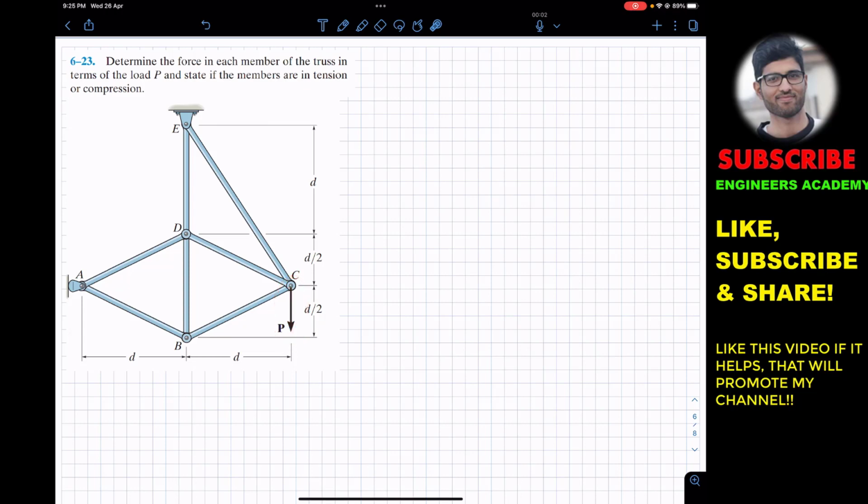So first of all, we will consider the whole truss and we will find the support reaction. So at E, let's say that we have EX reaction, which is going towards the right, and let's say we have EY reaction. And similarly, at A, we have the roller support. So at A, we will have only one reaction and that must be acting towards the right. So this is, let's say, AX.